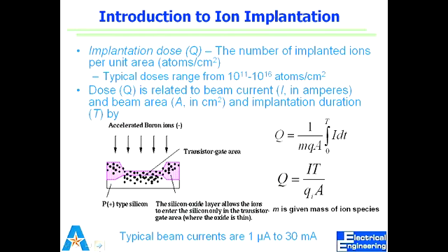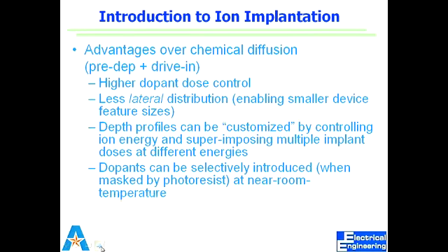How deep do we want those ions to travel within the substrate? And a thicker mask would be where we want to arrest them. We don't want them to go inside. So this is an example of where we have silicon dioxide on top of silicon, right?